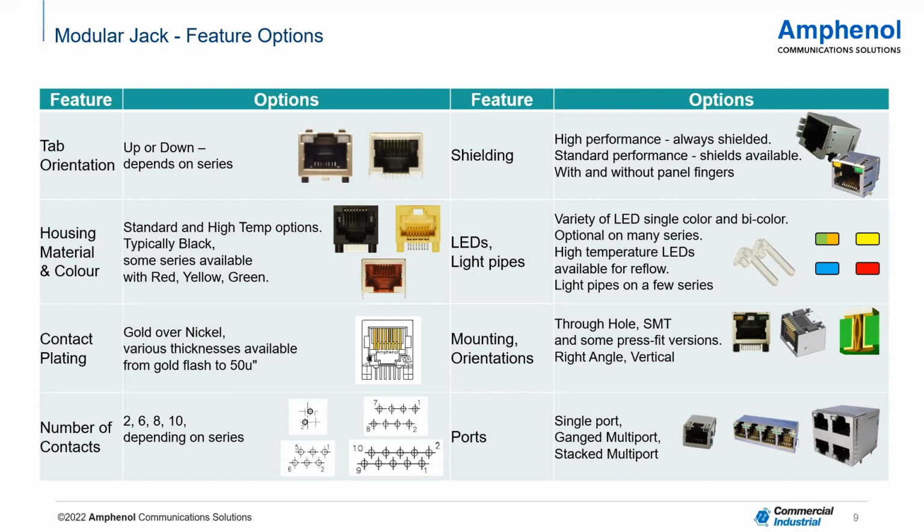Various LED options, you can have multiple colors in the LED, you can have bicolor LEDs. We also have certain series that we offer with LED light pipes. We have multiple mounting orientations. You can have through hole, you can have surface mount, you can have press fit. And also the number of ports, you can have ganged multiport or a stacked multiport or a simple single port.